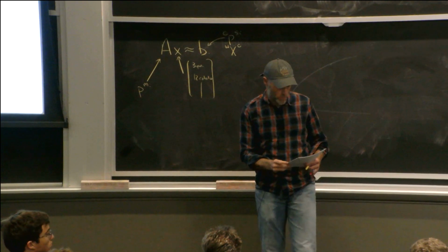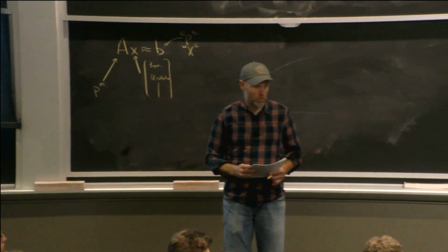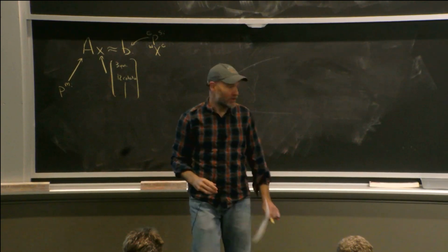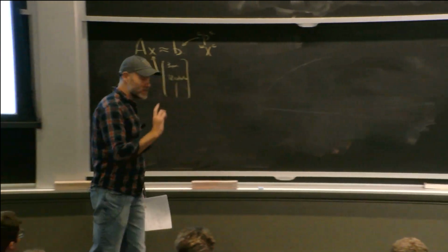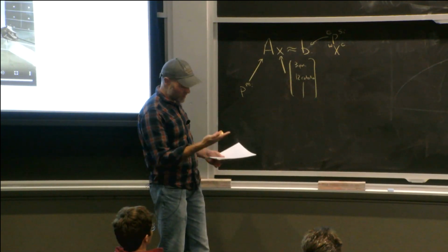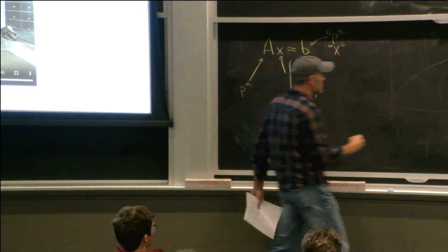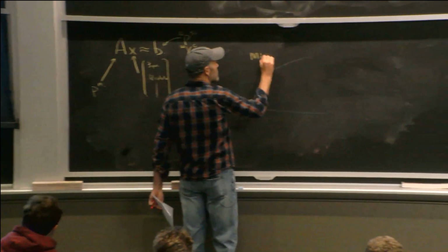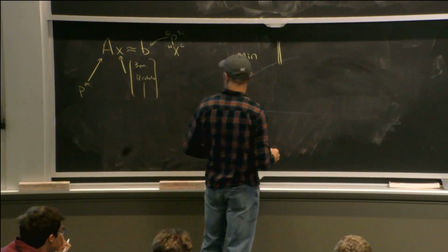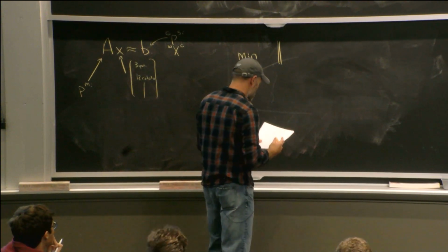Yeah. Is this going to give you a valid rotation matrix? That's exactly the, yeah, so you got it right. So the reason I said almost, he says, is this going to give you a valid rotation matrix, right? So what I really want to write in an optimization world is I want to minimize the difference between the right and the left-hand side. This is basically my AX minus B, okay?